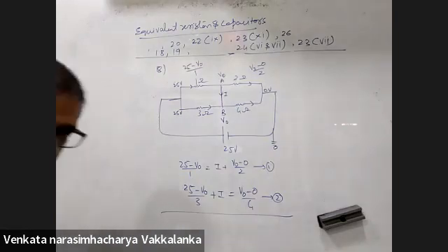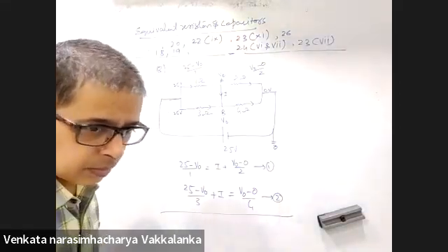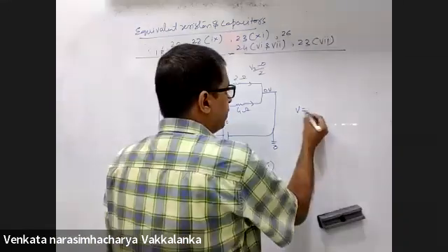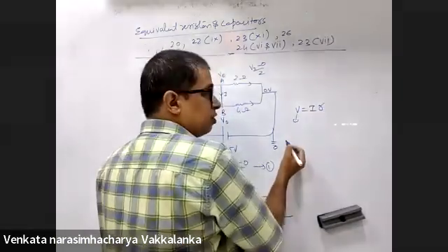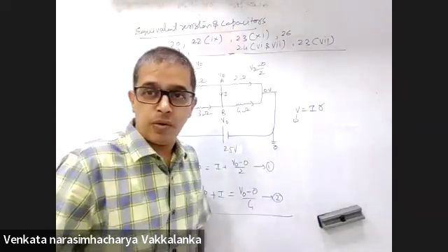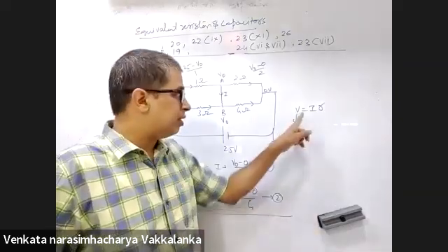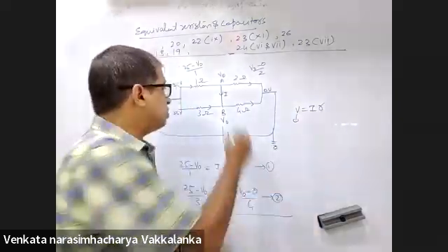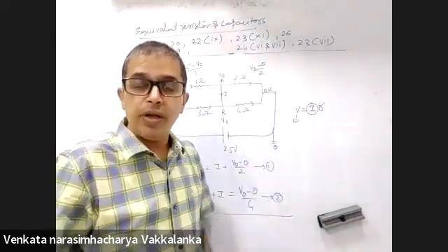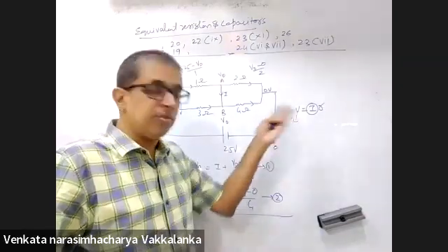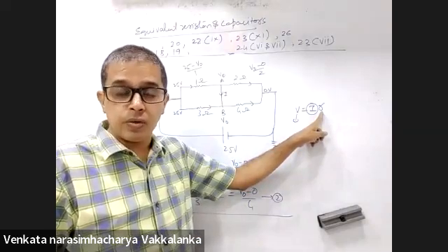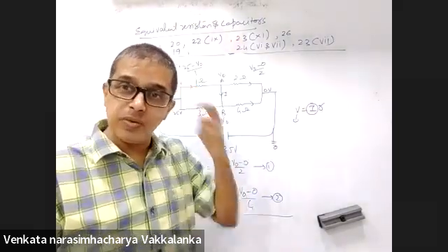Sir, why will any current flow through the AB branch because the potential difference is 0 there? Listen carefully. V equal to IR. Potential difference is 0 either when current is 0 or resistance is 0. Resistance is 0 here, so potential difference is 0. Current need not be 0. In 90% of the cases, this will be the situation ironically. V will be 0 when resistance is 0.